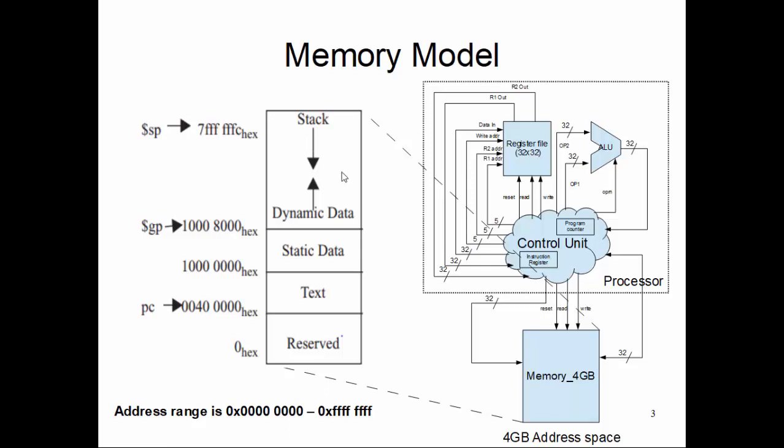The other part: since it has a 32-bit address space, your address values range from all zeros to all Fs, right? But in this picture, our highest point of being able to access is 7FFFFFFC. So what happened to the rest of the memory, up to FFFFFFFF? That part is also reserved, but this time for the operating system. By convention, that part is reserved for the operating system. We'll see that in the next slide in a minute.